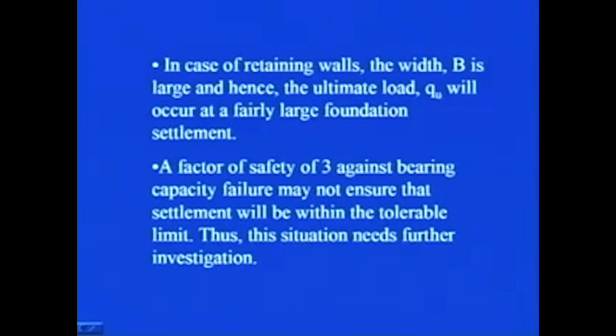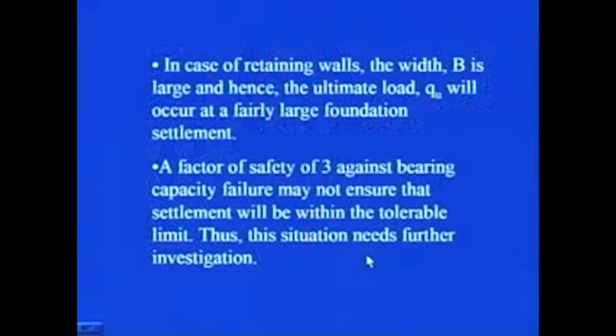As it is beyond the scope of this course, I am not discussing all these things in detail, but you must always remember that although the wall is safe against the three aspects, that is, overturning, sliding and bearing capacity failure, due to large or excessive settlement the serviceability criterion may not be satisfied. So, in that condition we need to take proper care.